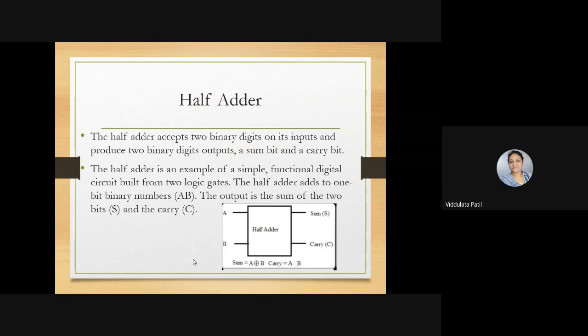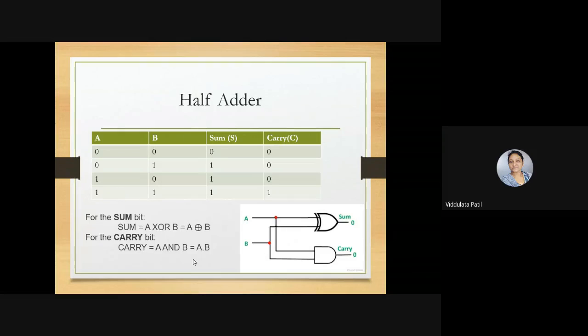Okay. So this is a very simple circuitry that we are going to discuss first, and after that we are going for the simulation of this program. Okay. So when we are discussing the output for half adder, output sum is nothing but A XOR B, and the other output, that is carry, is A AND B. Okay. So these are the Boolean expressions for the output of half adder. Okay. Everyone knows about this.